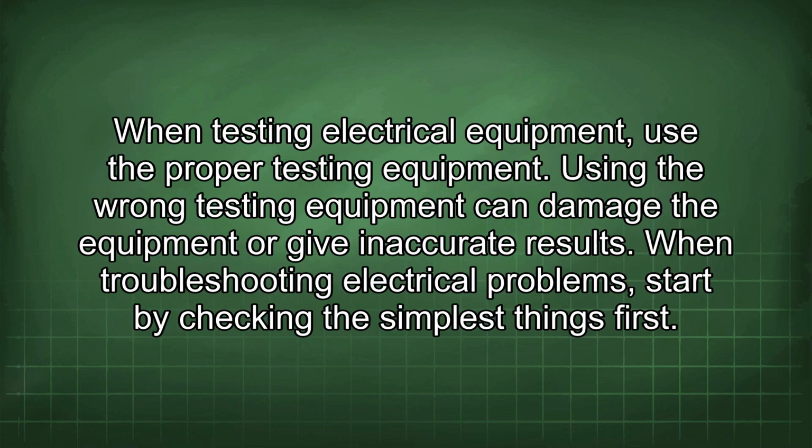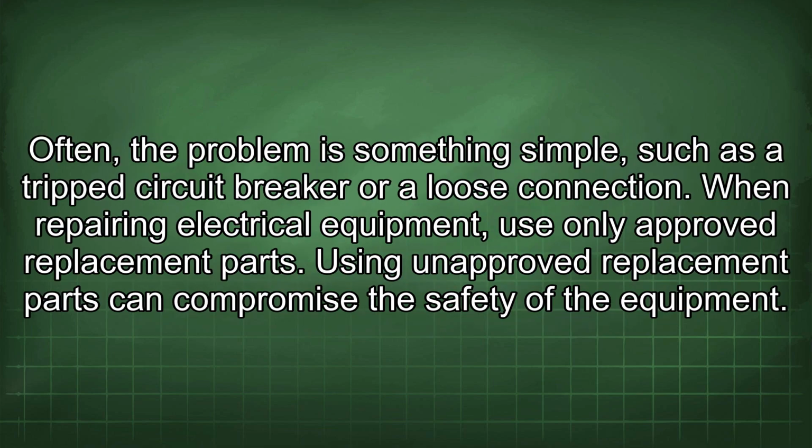When testing electrical equipment, use the proper testing equipment. Using the wrong testing equipment can damage the equipment or give inaccurate results. When troubleshooting electrical problems, start by checking the simplest things first. Often, the problem is something simple, such as a tripped circuit breaker or a loose connection.